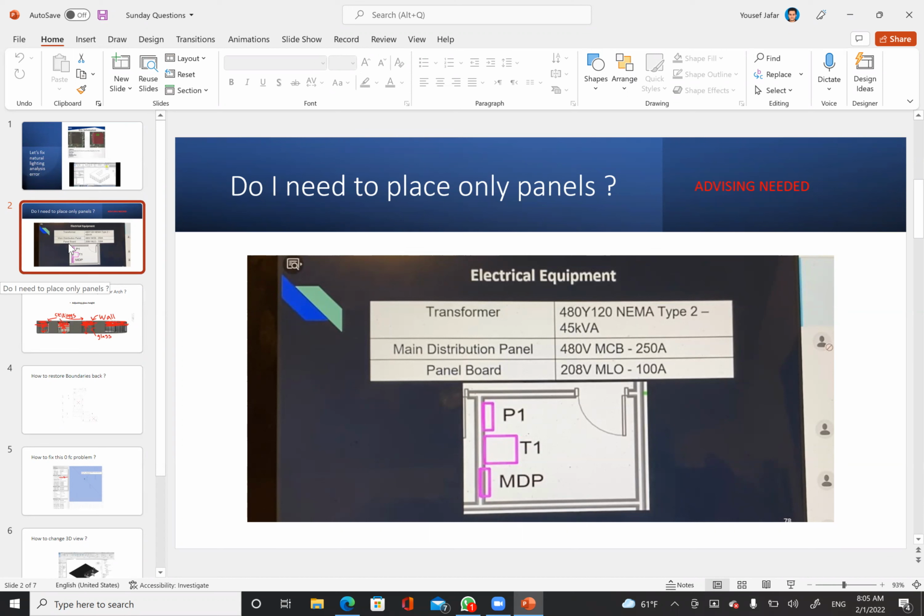Then I asked you, because ducting is not a problem. It can be with ceiling or without, but lighting is a big problem, you know, you need to decide what kind of ceiling. Every area will have different ceiling, because of what kind of things you have in that space, and what you want to expose, which area you want more. So this is very good. Like, you have found out that now suspended ceiling for this one is there, educational place and gift shop, beam ceiling for entrance.